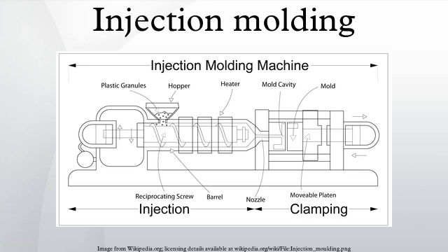Dimensional differences can be attributed to non-uniform, pressure-induced deformation during injection, machining tolerances, and non-uniform thermal expansion and contraction of mold components, which experience rapid cycling during the injection, packing, cooling, and ejection phases of the process. Mold components are often designed with materials of various coefficients of thermal expansion. These factors cannot be simultaneously accounted for without astronomical increases in the cost of design, fabrication, processing, and quality monitoring. The skillful mold and part designer will position these aesthetic detriments in hidden areas if feasible.